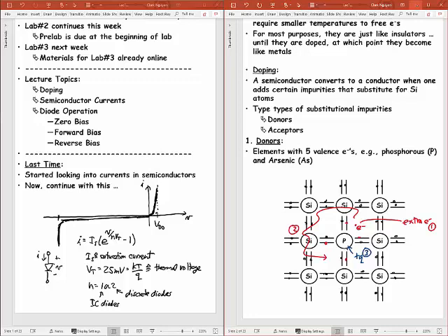But if we go ahead and replace the silicon with a phosphorus, which is what we did last time, what happens is 4 of the phosphorus electrons go into place in that valence shell to give phosphorus and the silicons around it all 8 valence electrons, where they're at their happiest. And happiest means that's their lowest energy state. Okay, so their lowest energy state is when their valence band is filled, but now phosphorus has got a 5th electron.